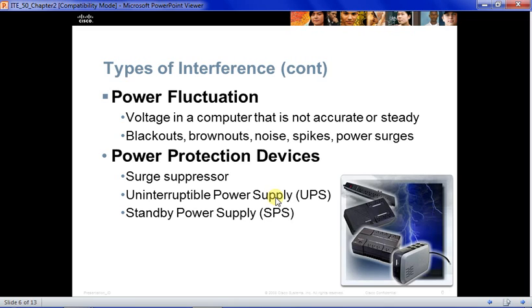One of the things to note is you should not plug your printers into a UPS, because when printers such as laser printers go to print, they usually drain power. They increase the wattage they draw, and this could burn out the UPS.